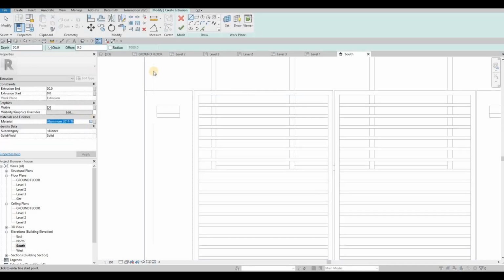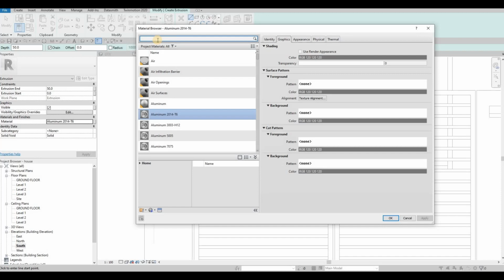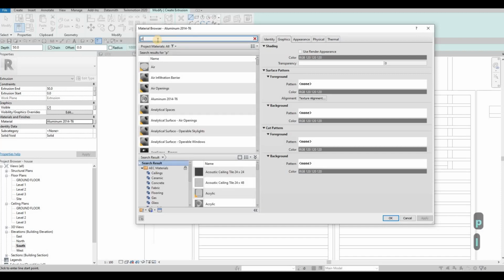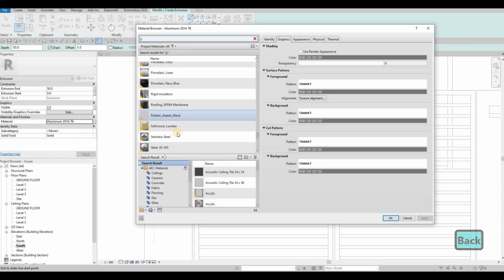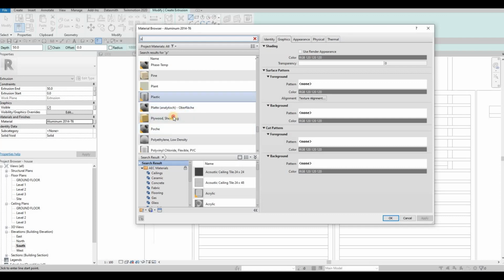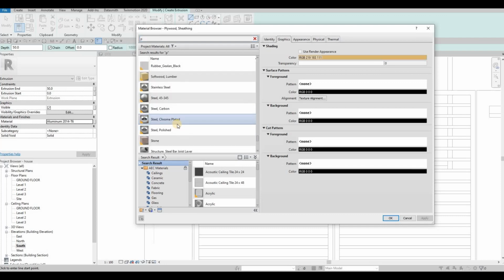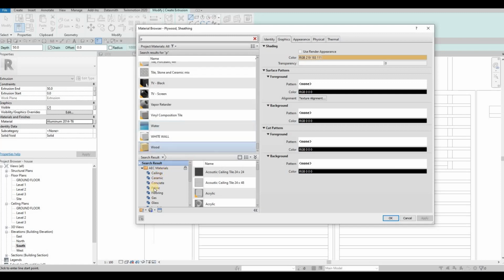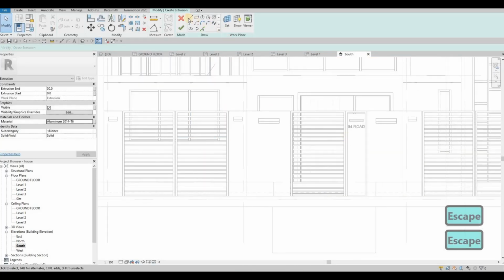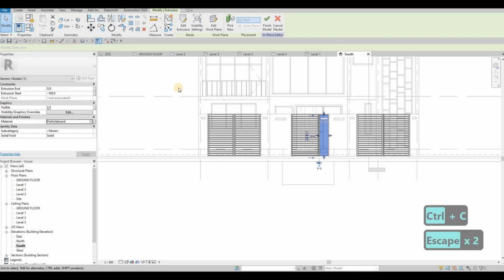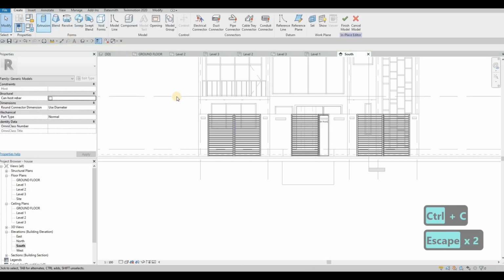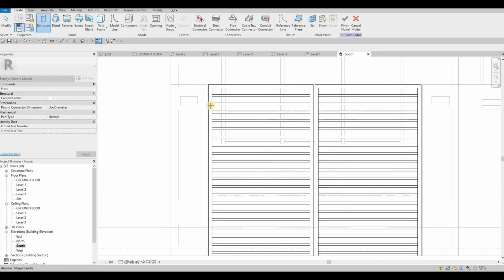And then I know we put in the wood material, plywood sheeting, I think. So let's go to wood and see what we selected before. I'm gonna close this off. Particle board. So here I'm gonna use particle board. Let's make an extrusion.